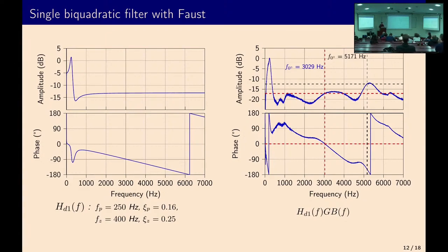But in this case, there is a particular and interesting phenomenon: for this frequency response, which corresponds to one position of the headphone and one position of the microphone, the control microphone, shifting the frequency, for this new unstable frequency, the amplitude is actually lower, which means that now we have a bigger gain margin. So normally we'll be able to increase even more the gain and obtain a better noise reduction. So we will see in a little bit if it is true.